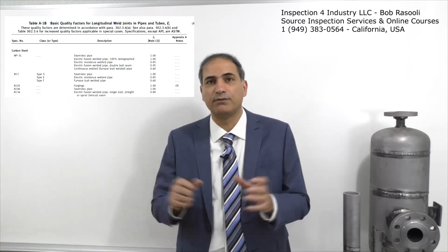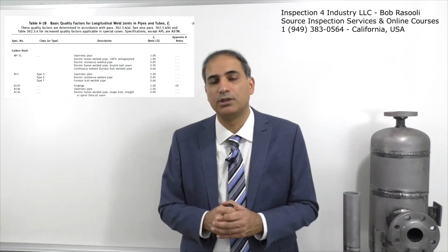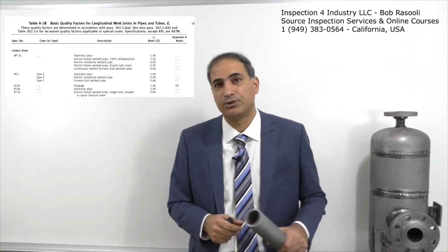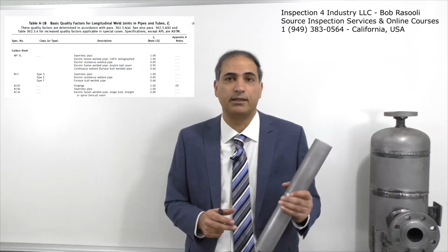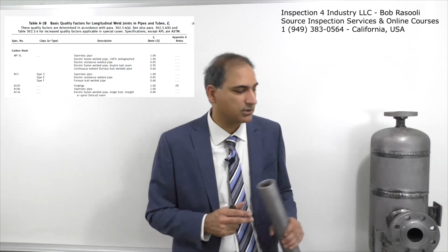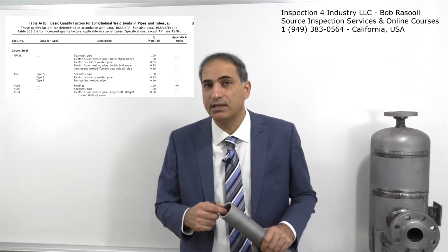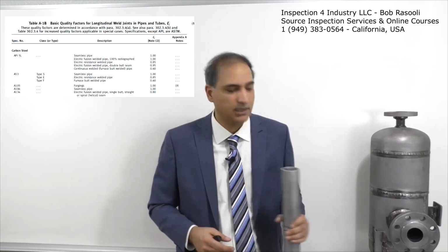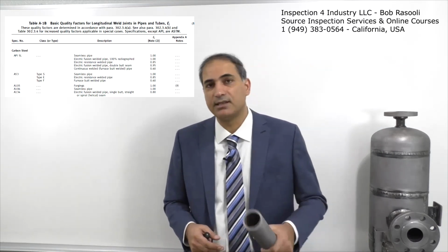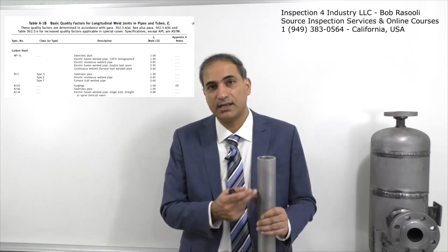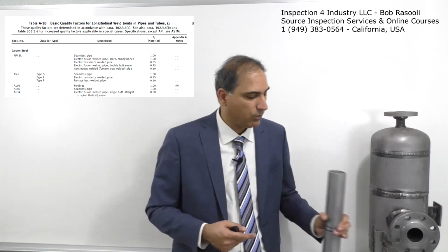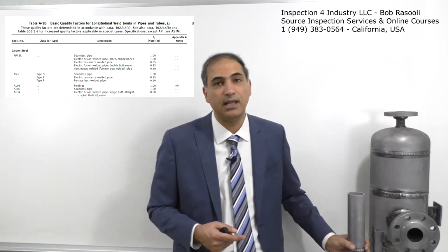But there's a table for both of them, and we are mostly going to use the A1B table for regular piping, which is manufactured by a process other than casting, by rolling and drawing. Either they are seamless pipe, electric resistance welded pipe or fusion welded pipe. This pipe, as you can see, is a seamless pipe, so there are no seams in here. I'm not talking about the circumferential joint, I'm talking about the long seam. In this design formula, E is talking about the long seam.